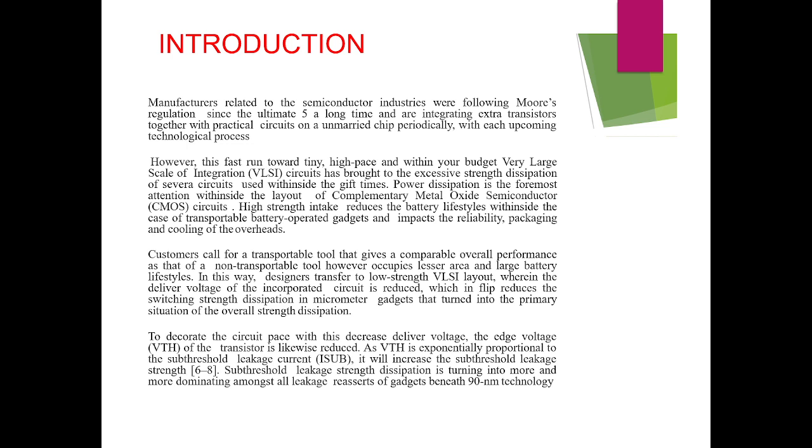The transistor we are going to use in our topic is the PMOS transistor. PMOS transistors operate by creating an inversion layer in an N-type transistor body. The inversion layer, called the P channel, can conduct holes between P-type source and drain terminals. The P channel is created by applying a negative voltage, up to minus 25 volts, to the third terminal, which is called the gate. So moving on, Pritesh will carry on.